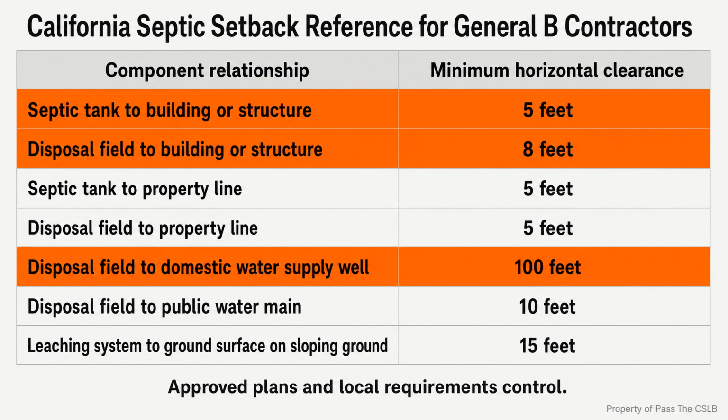Suppose an excavator breaks through an undocumented cesspool during grading for an addition. That is a hypothetical project, but the field decision is realistic. The contractor secures the area and stops treating it like ordinary dirt work. Laborers should not simply push loose soil through the broken top and continue grading. The contractor coordinates pumping, removal of the top, complete filling, and the required approval before the area becomes part of the new work.